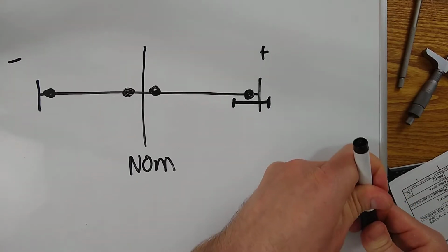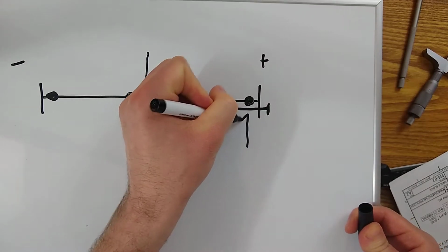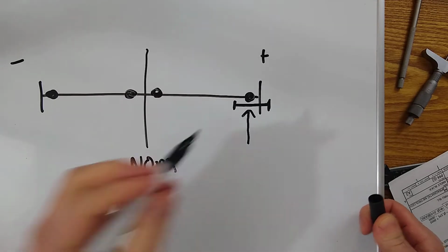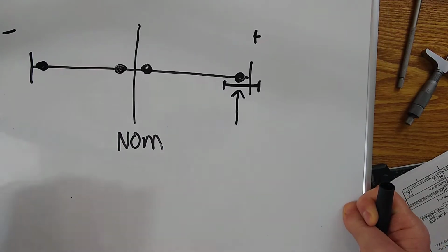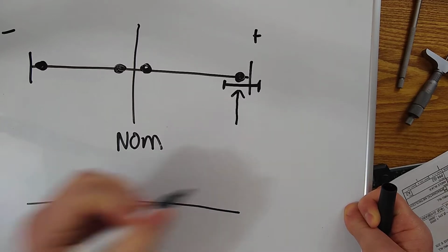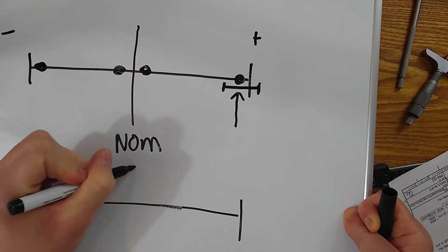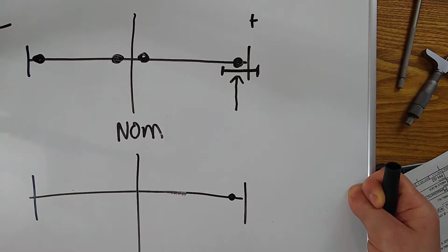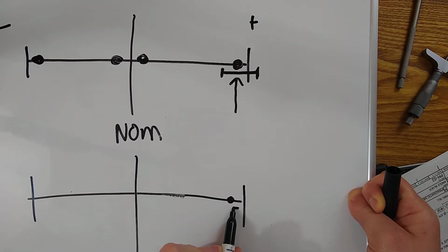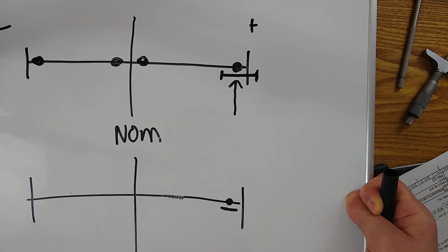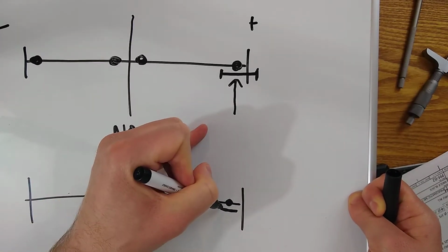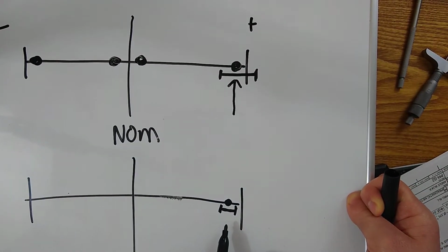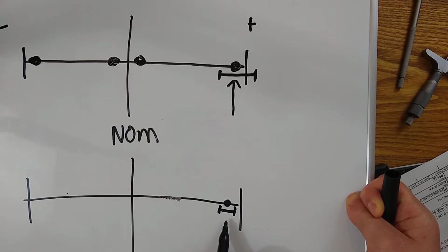So in situations where you end up close to the edge, you may ask yourself, ooh, I'm close to the edge, do I need to use something better? When I repeat that measurement and I get right on the edge, but I use a more accurate gauge that has a much smaller uncertainty zone, you're within tolerance in all cases.